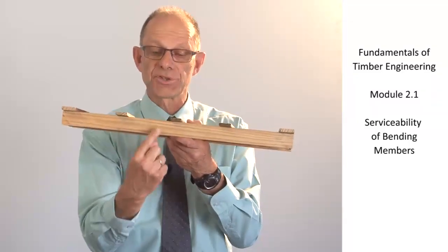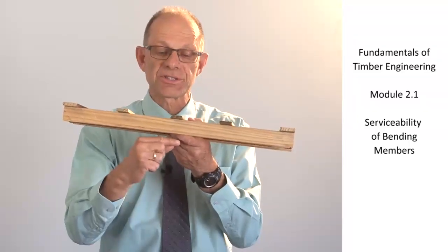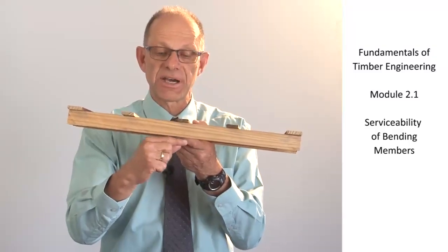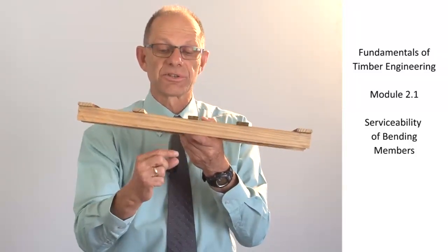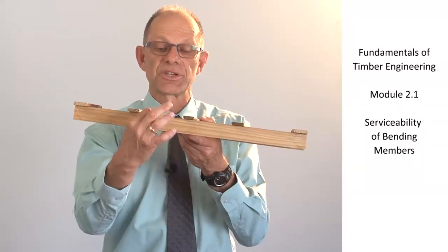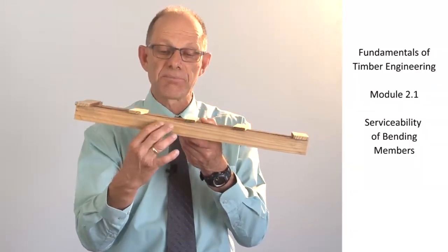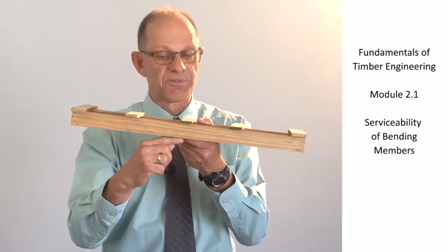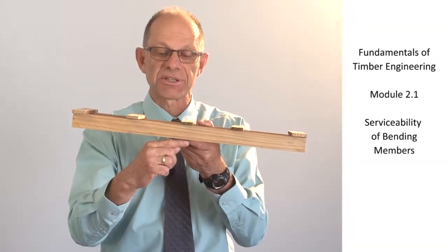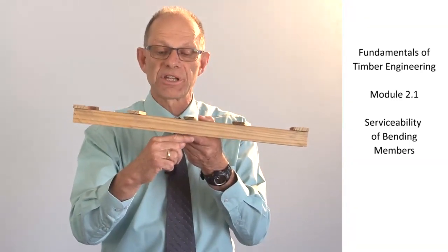And if that floor joist deflects too much, it's going to damage that partition. Its total deflection is important, so it's a combination of the imposed load and the permanent load on the joist, the sum of all of the loads on that particular joist, and we want to avoid damage to that